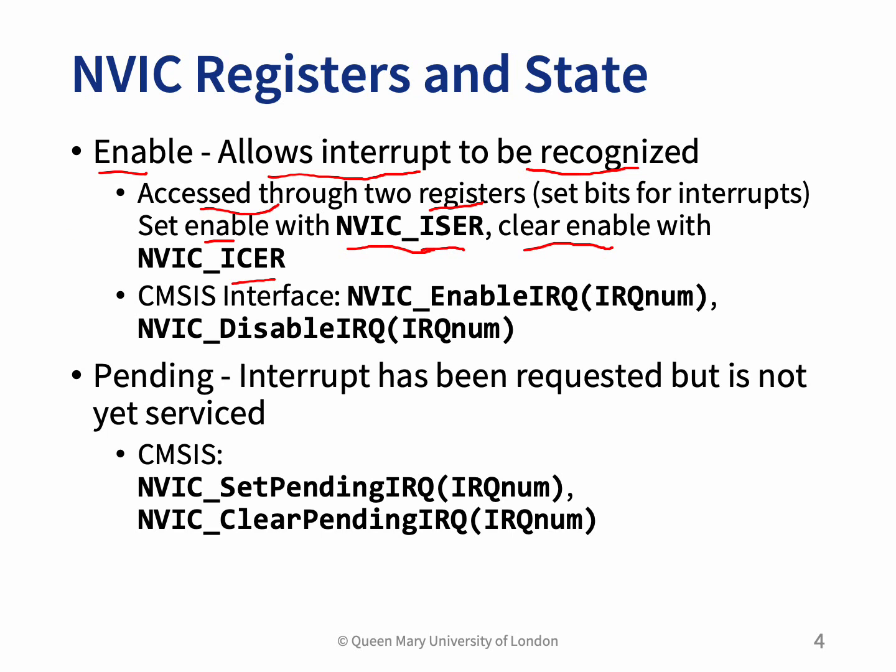These two are a similar way of allowing the interrupt to be recognized. But CMSIS provides a better interface, right? Allowing us to put the information in, and it will be recognized for the interrupt. So it is just enable IRQ or disable IRQ. It is very straightforward as it is. So note that these two are the same way for the NVIC to be recognized, right?